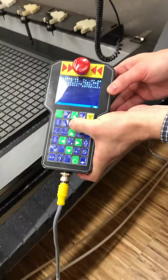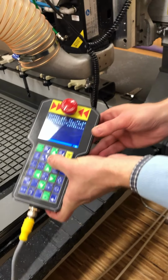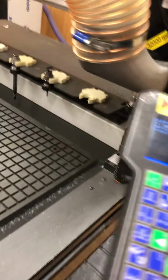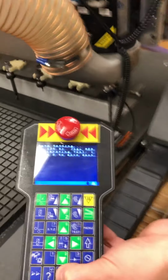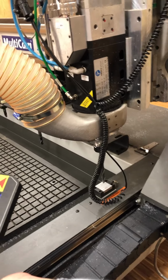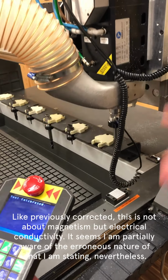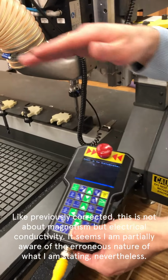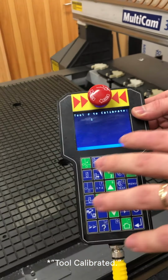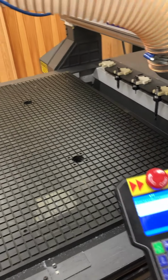So now we start by having the C jogged a little closer. And then we can see that we can move it actually a little bit closer here. And now we can hold down 0. So now we hold down 0. And as soon as it touches, I say magnetism, but yeah, as soon as it touches, then it knows, okay, I'm there. And it says, very briefly, that tool number 1 is calibrated. And then you can press cancel, and it is calibrated.